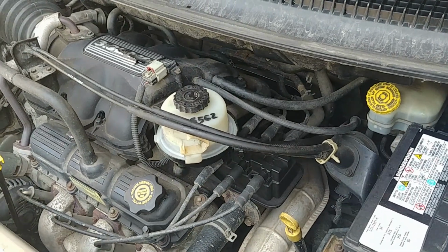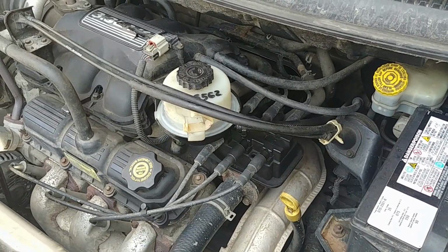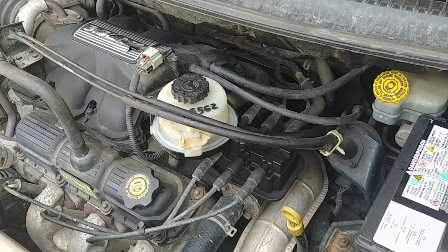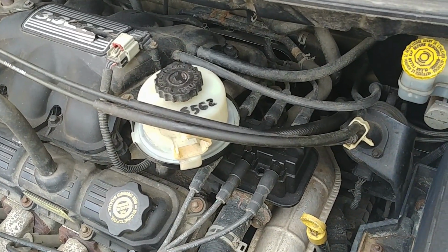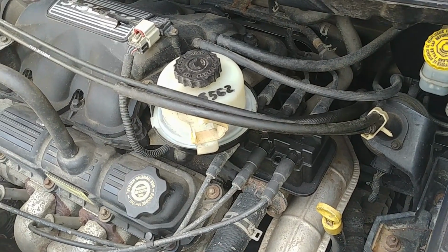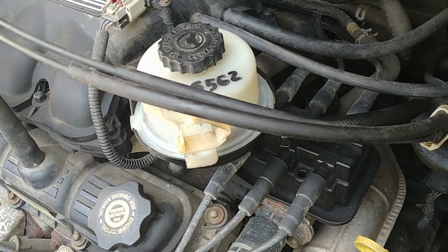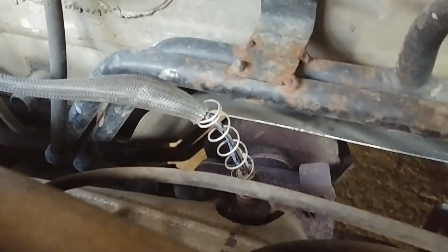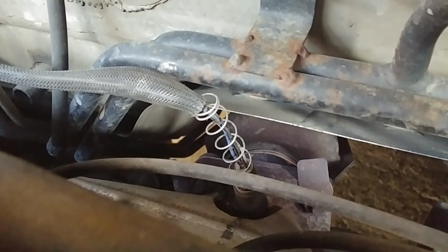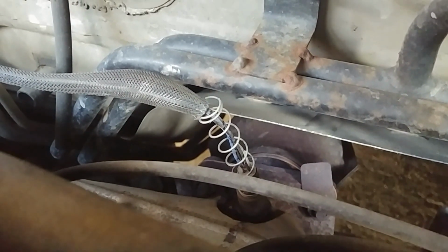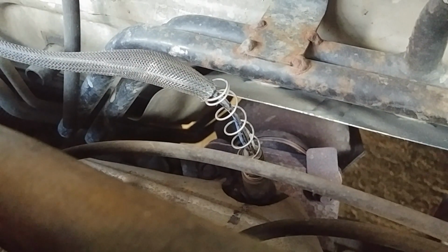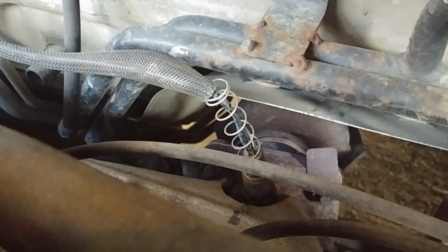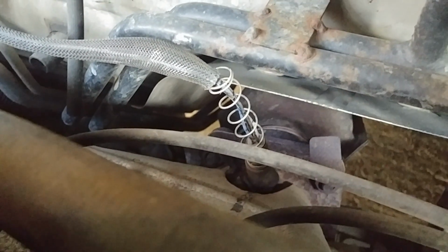In general, it depends on the manufacturer and model. There can be some variations, but the location of that sensor is the same. It's located just before the catalytic converter. It's sensor number 1, and I will try to show you. Here we go. There is a downstream pipe and down below the catalytic converter, and this is sensor number 1, which is known as the oxygen sensor, O2 sensor number 1.